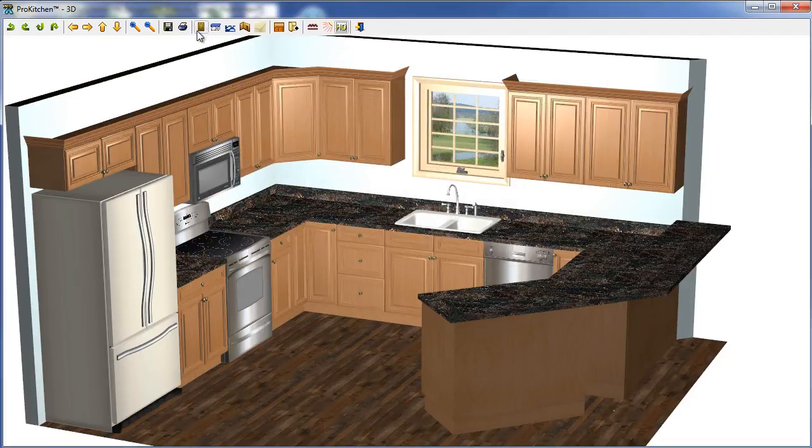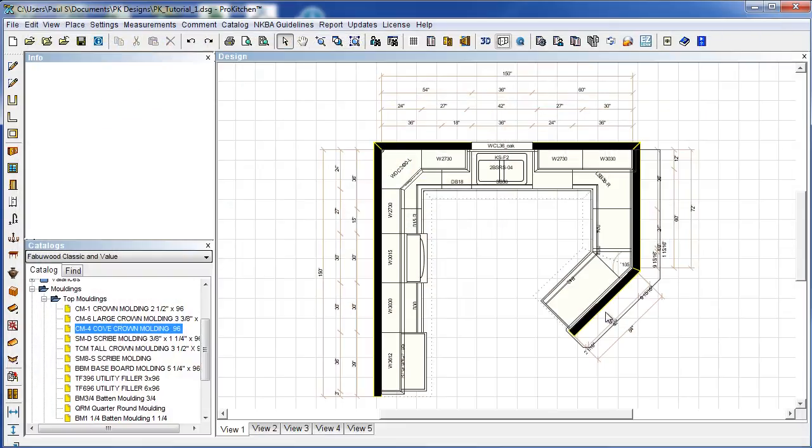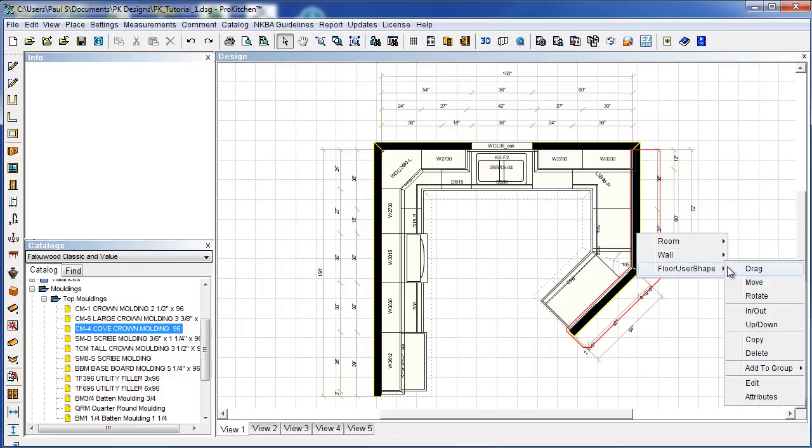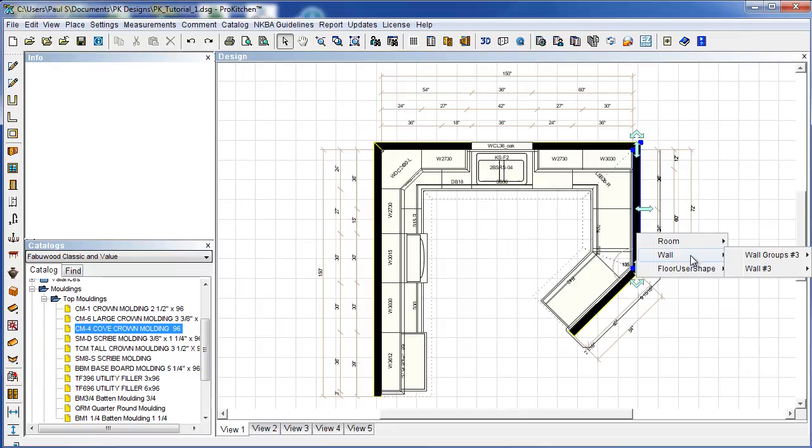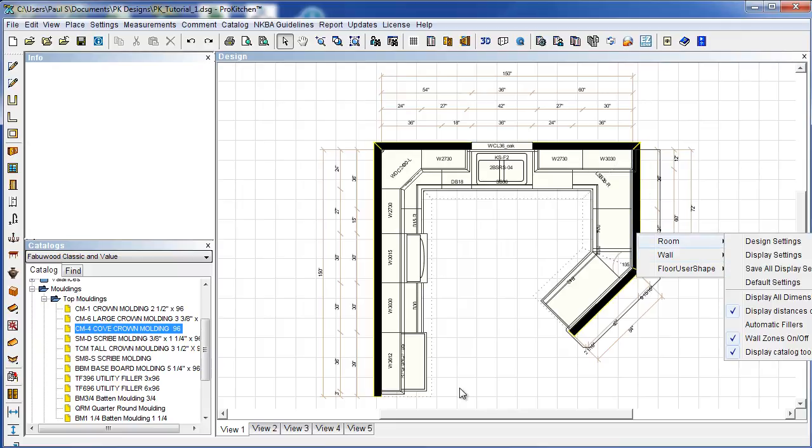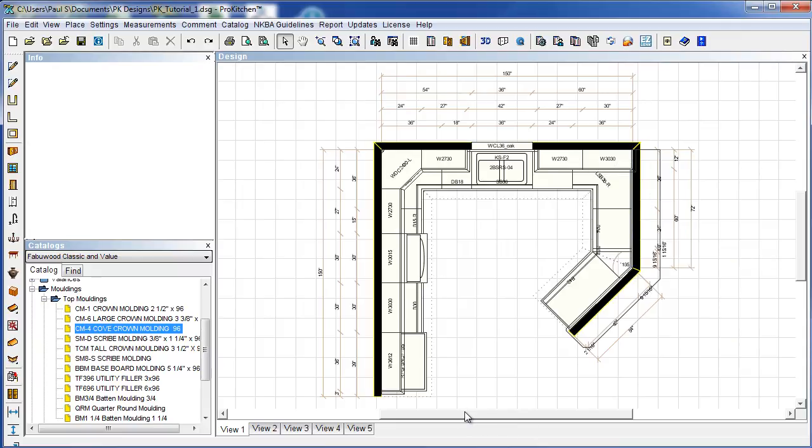We're going to take a look at a few of the other features up here, but before we do that, we're going to fix our walls. So we're going to close this. Now remember these two little walls that disappear up here? If you don't want them to disappear, we're just going to go to Wall and add Wall. Alright, come on over here.